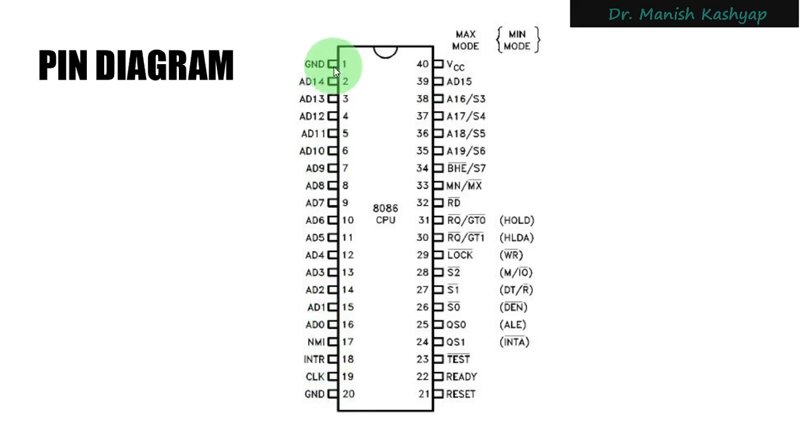The details of this might be known to you from your basic electronics circuit course, where you also learn that in a big circuit you have to have multiple grounds. Because of that reason, you have multiple grounds here. So VCC and these two ground pins have to be appropriately placed: VCC at plus 5 volt DC, and at the ground pins you have to give the ground signal.